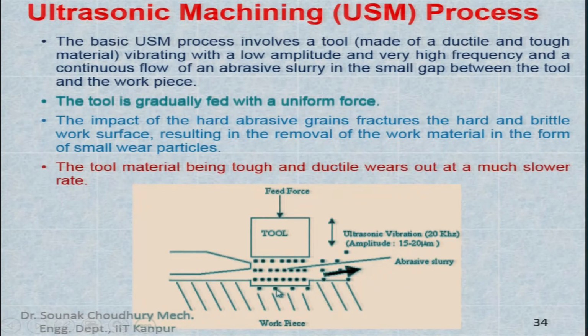Therefore, the frequency and amplitude given by the tool are imparted on each of these particles, and with that frequency and amplitude they impinge the surface, which is a brittle surface of hard material. So it will fracture, with a brittle fracture, and that fractured material piece will be removed from the surface.